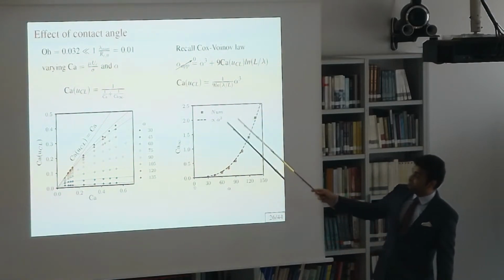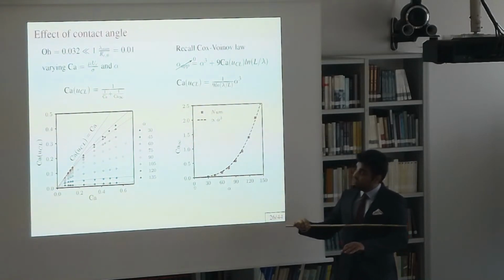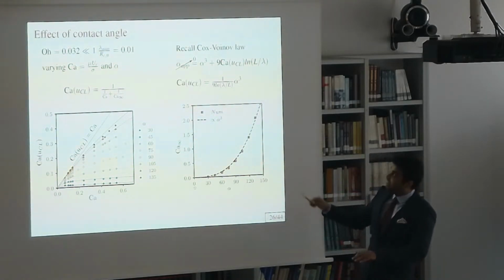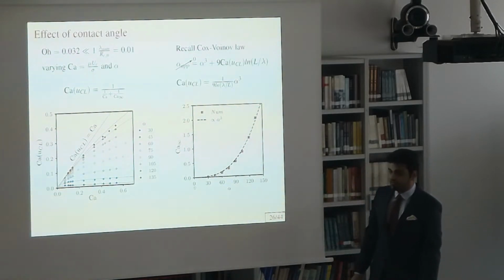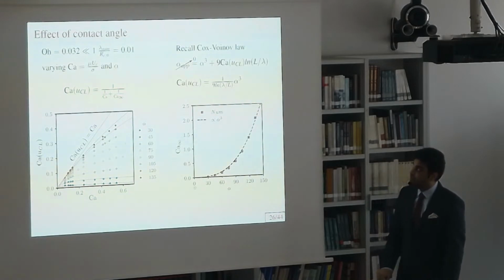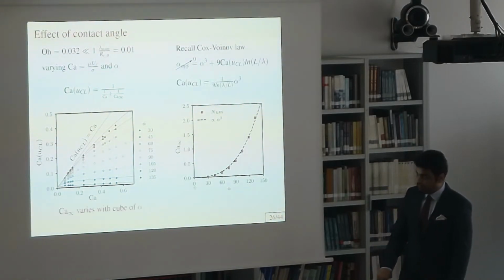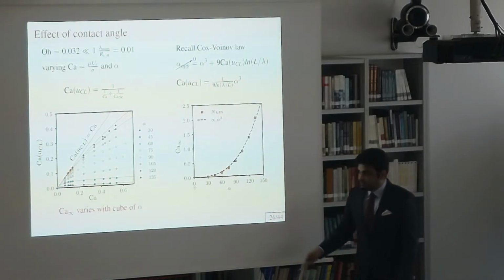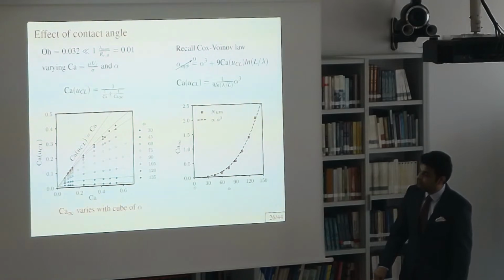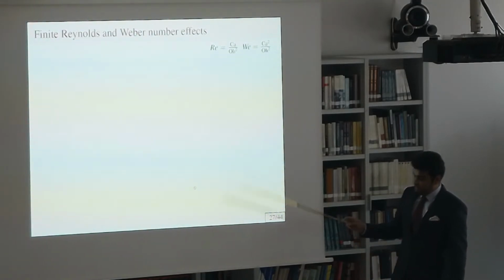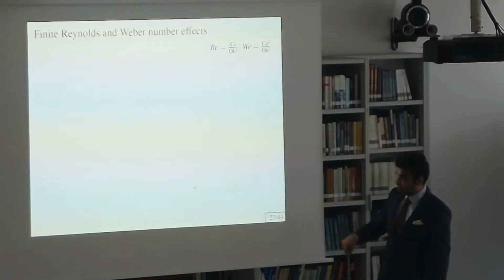And we can argue that when the microlayer is formed, the bubble becomes flat and this angle tends to zero, and one can recover the cubic dependence of the contact line capillary number on the angle, which is put at the smallest grid size. This is the conclusion from this slide. And now to remind you that I was working in the large Reynolds and Weber number regime.